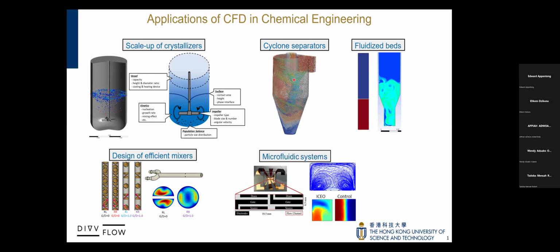You are basically solving Newton's second law, so you end up tracking each individual particle, compared to an Eulerian phase where you have a volume fraction term, which then defines your phase.